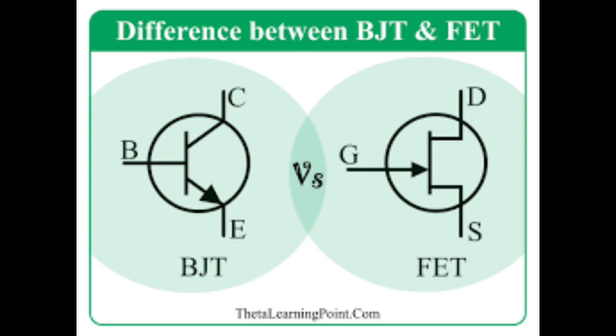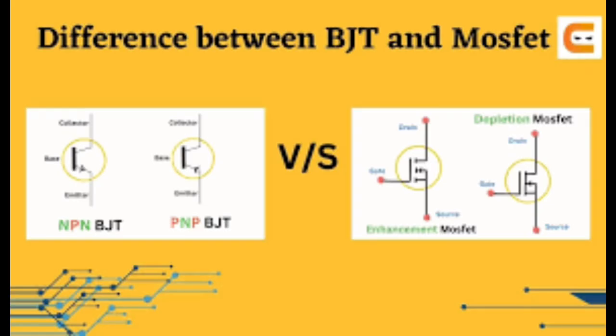Number 3, determine NPN or PNP. If the base is P-type, positive probe on base shows a drop, it's an NPN. If the base is N-type, negative probe on base shows a drop, it's a PNP. Fourthly, confirm terminals. Once the base is identified, test the remaining two pins, collector and emitter. The collector-emitter path should not conduct in either direction without base current.